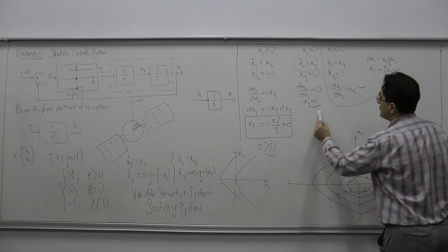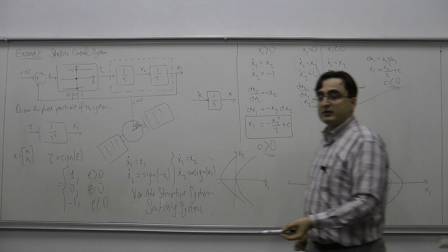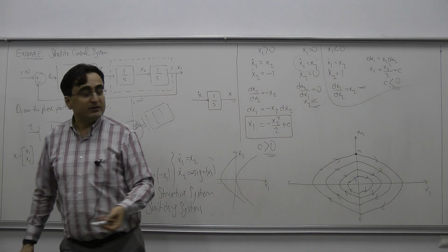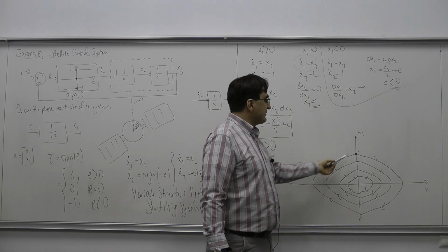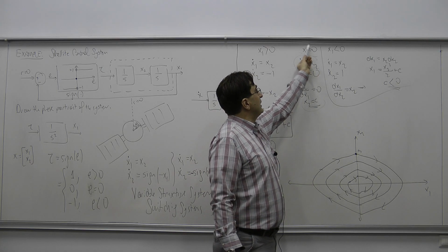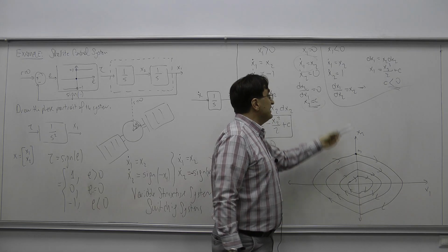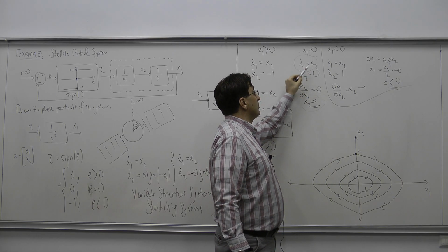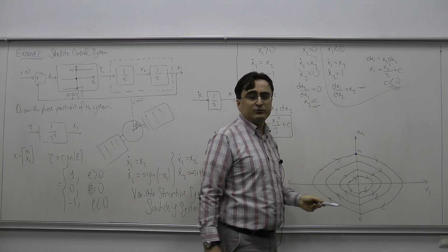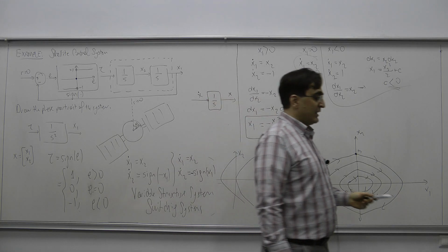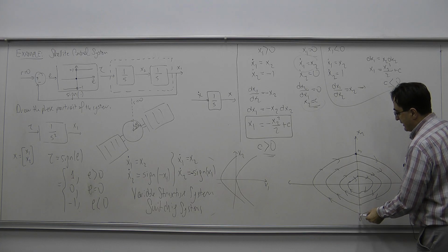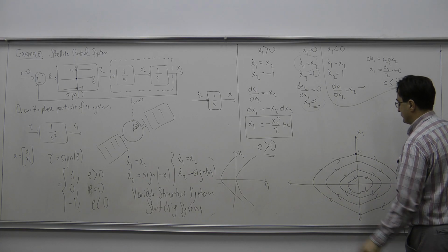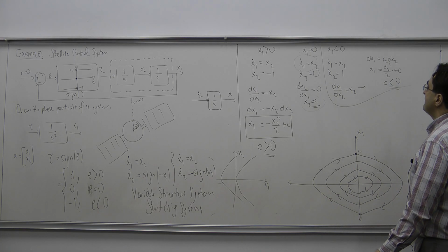So this x2 equals constant dynamics is never seen in this case, because even if x1 comes to the value 0, it immediately leaves that value because x1 dot is equal to x2, okay? And then x2 being positive or negative would immediately make the system leave the x2 axis, okay?